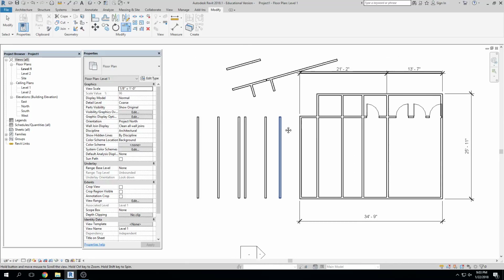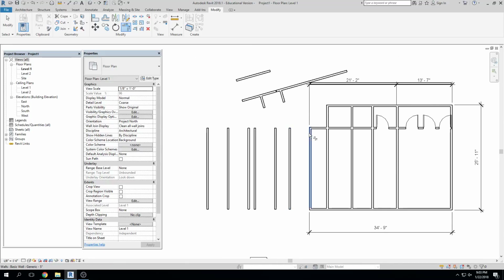The key to trimming is just making sure you somewhat pick them in order. What I mean by that is I want this one to trim up to there. Well, this might be a bad example, but let me just keep going till I find one. It can go the opposite direction, which is hard to see right now, but trimming can very easily go the opposite direction. So instead of something trimming together, if you select it incorrectly, it will kind of go off and look really goofy and make a V, okay? And you'll find that out. So let's do, oh, see, there's a good example right there.